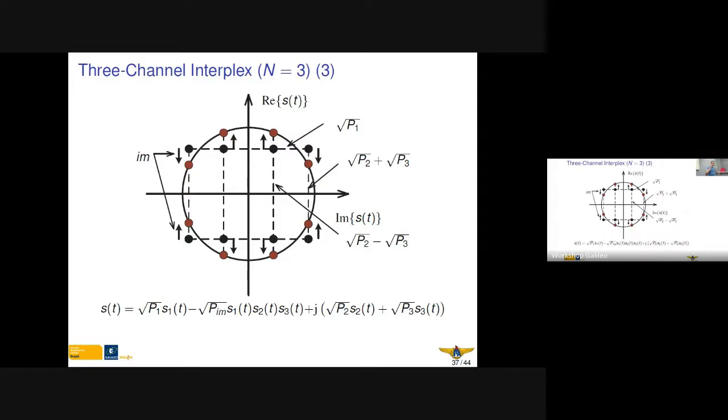If the signals are not binary, which in reality is the case when they are generated, we may have to introduce a little bit of back off in the amplifier, but we can still operate very efficiently due to the intermodulation product. However, this costs power. Some of the power that could be used for the useful signals is directed to the intermodulation product to ensure this constant envelope.